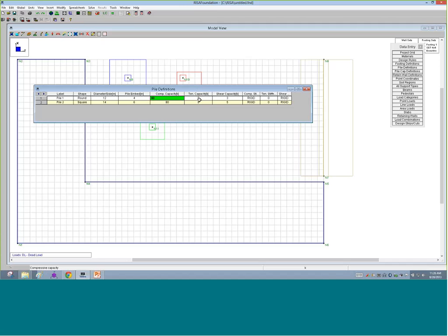So our default has the program allowing no uplift in this pile, which is kind of a common occurrence, but maybe yours has a special case where you can allow a tensile, so you can add a new type in there. But the other kind is that you can set these capacities, and beyond the capacity, we also need to tell the program what this pile is doing.